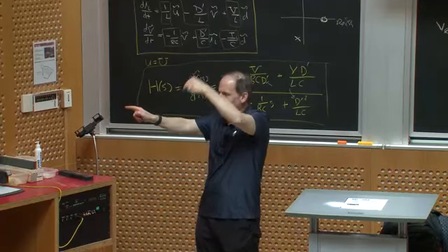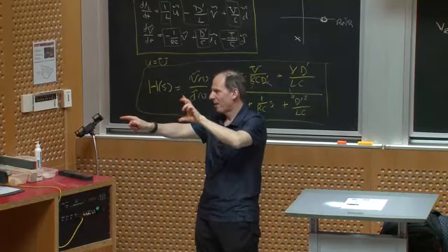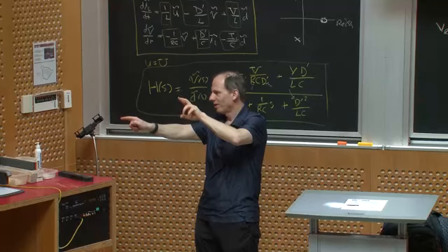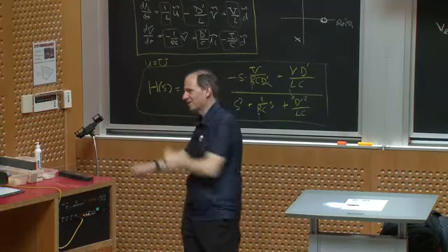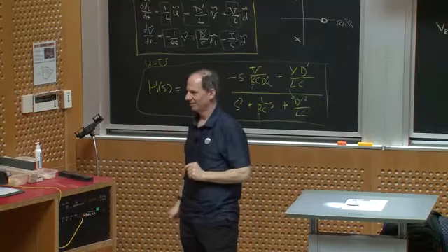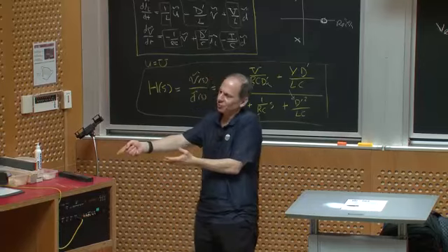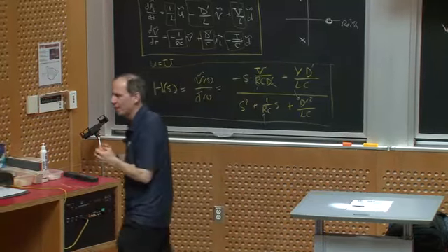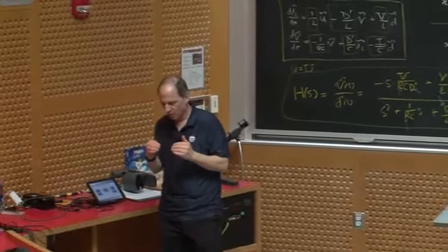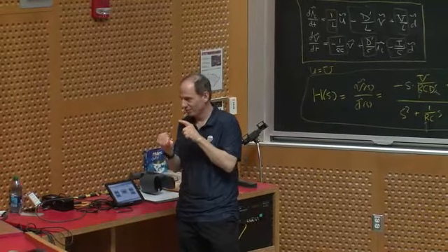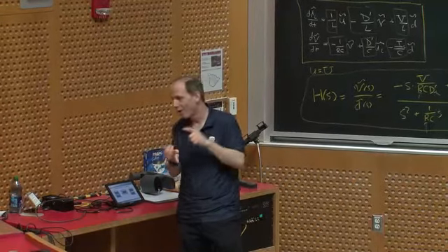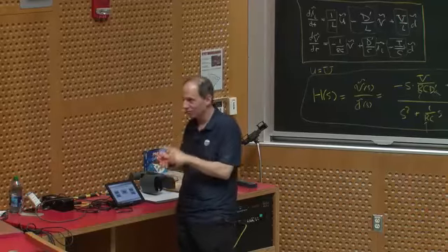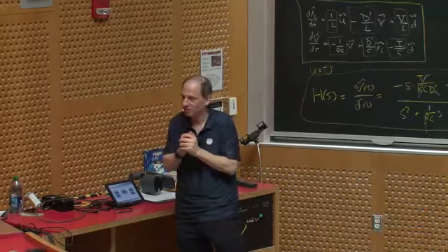And that little response may be bad. So if your power supply is wiggling around, a little bit of that gets into the output, and you don't like that. If what I'm feeding is a resistor, maybe you don't care. It depends on the application, but a lot of the time, if it's a power supply for an instrumentation amplifier or for an RF transmitter or a receiver, you've got to keep it very clean.